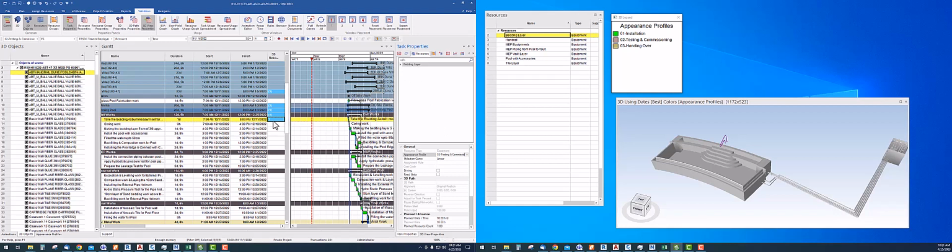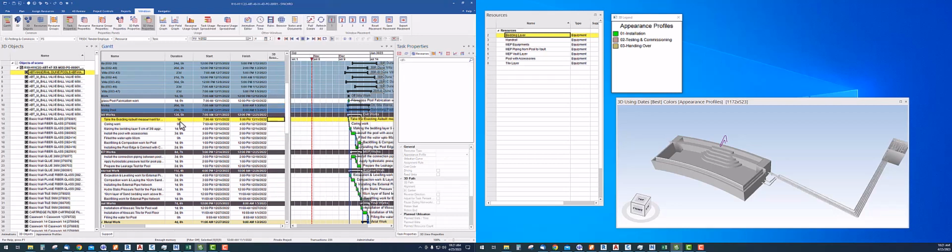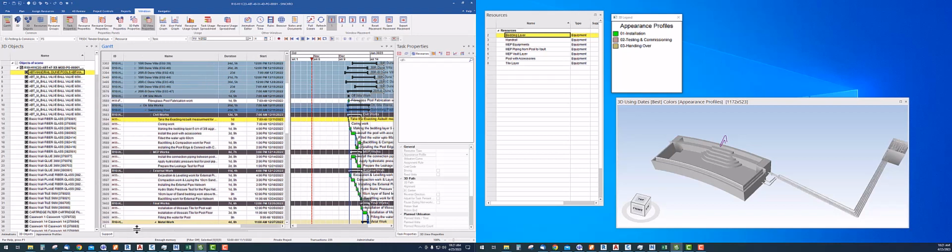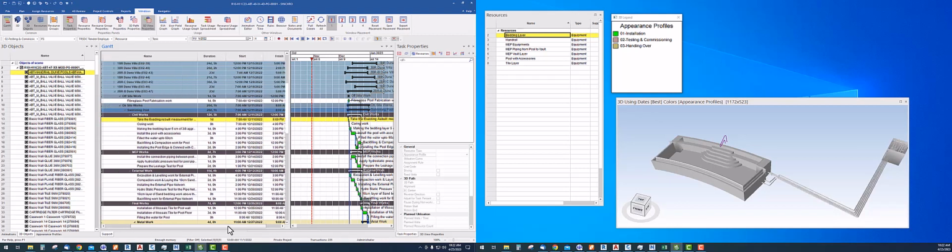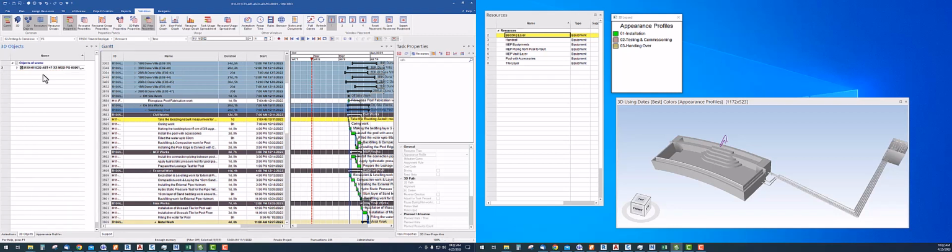Okay, so in case I don't want it, I will right click on the task and choose unassign all resources. So this bedding layer is unassigned from that task. Now it's removed. Everything should be linked to the tasks, then only we can create a 4D. Because if we do not link with the task, how will the 3D animate according to the timeline? The task has the timeline. You see this duration, start and end. So Gantt chart is the first process. Now this was the quick introduction.